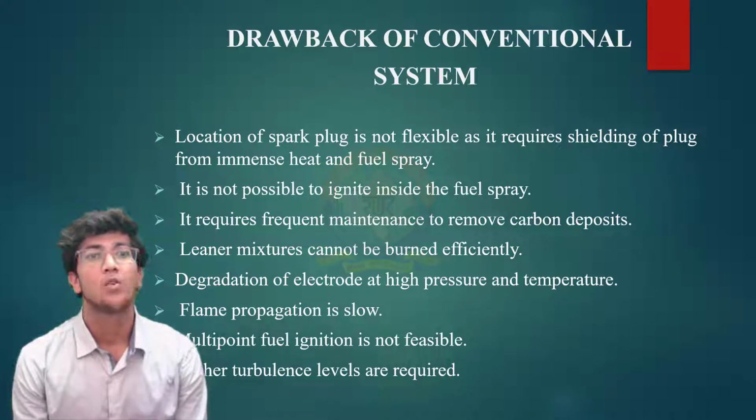Let's know about the drawbacks of conventional ignition system. The location of the spark plug is not flexible as it requires shielding of plugs from intense fuel spray. In conventional spark plug, the location of the spark plug is fixed as compared to the laser induced spark plug. It is not possible to ignite inside the fuel spray. It requires frequent maintenance to remove carbon deposits. Lean mixtures cannot be burned efficiently. Degradation of electrode at high pressure and temperature. Flame propagation is slow. Multi-point fuel ignition is not feasible. Higher turbulence levels are required.